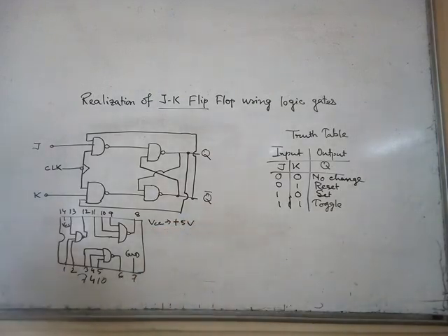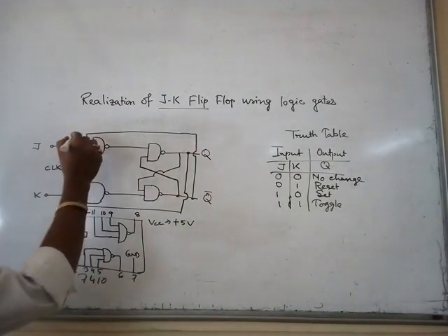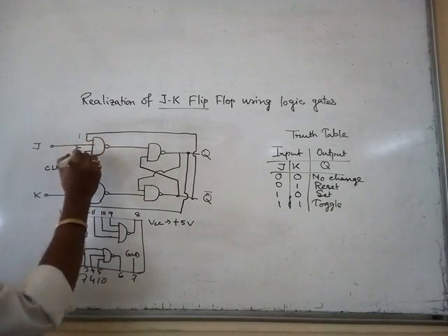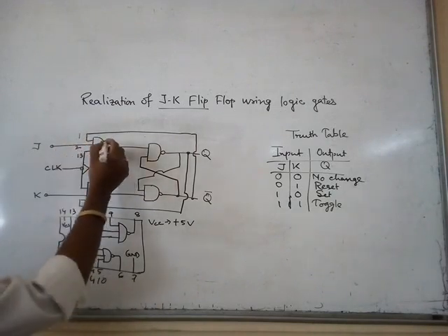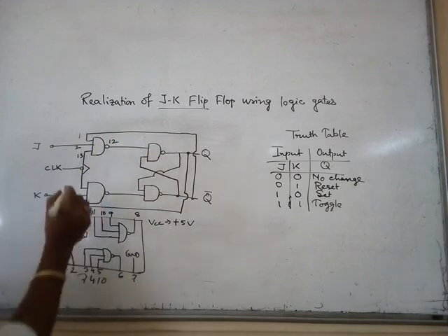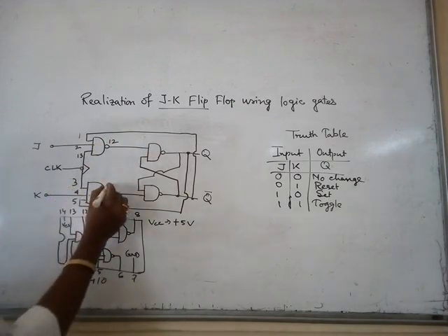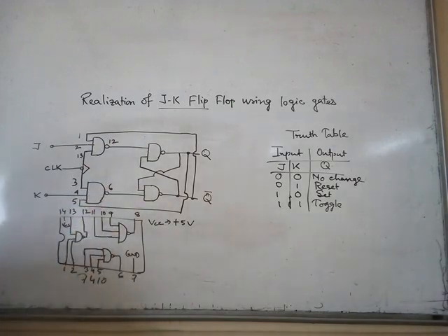So we have to give the pin numbers from the pin diagram of the 7410 IC. Now you can consider 1, 2, 13 as inputs and 12 as output, and next 3, 4, 5 as inputs and 6 as output. Next we go to the other gate.